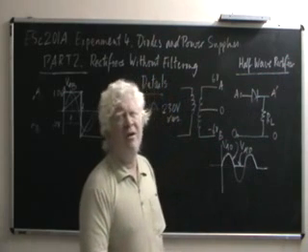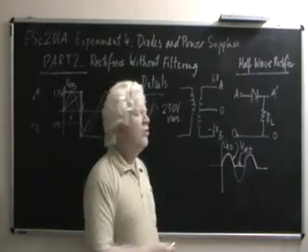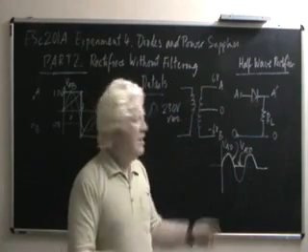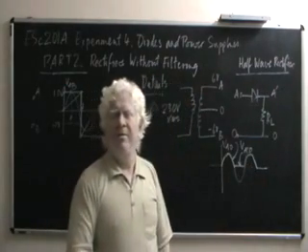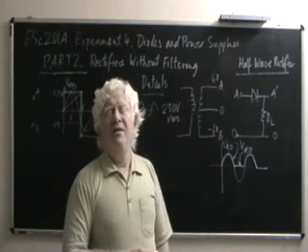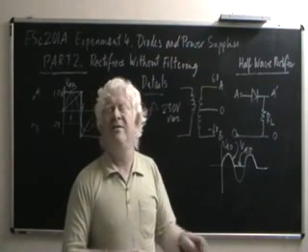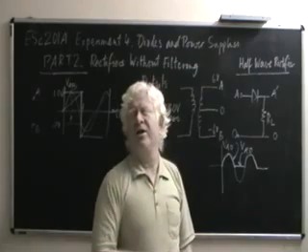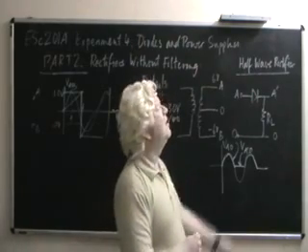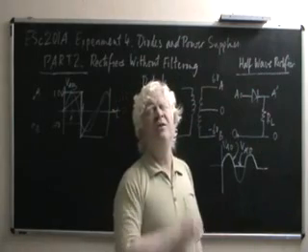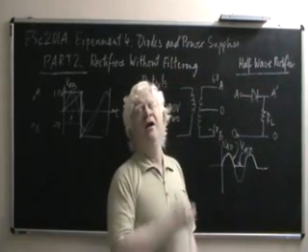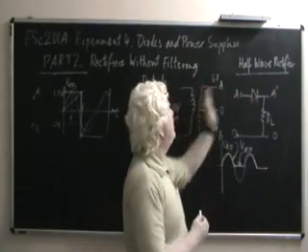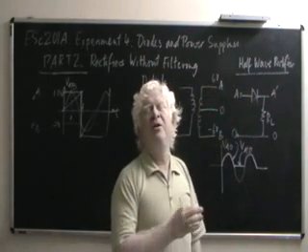One might argue that this half-wave rectifier is not a very clever thing, because while something is happening in the positive cycles, the circuit is just idling in the other half. That is valid, but this is not to say that power is being wasted in any way. Because you see, the resistor carries no current in the negative half cycle, and it carries the current only in the positive half cycle. So if you measure the power consumed by the resistor, it is, assuming the diode to be ideal, equal to the power being supplied from this side. No power is being wasted.